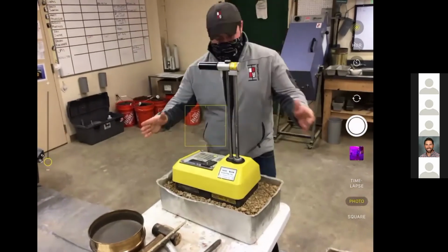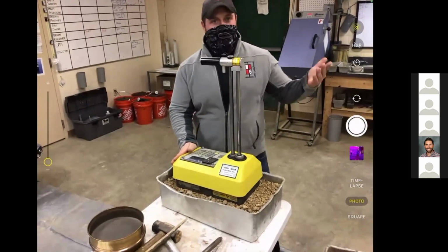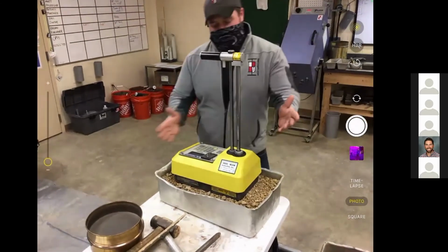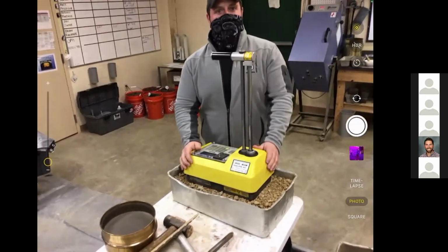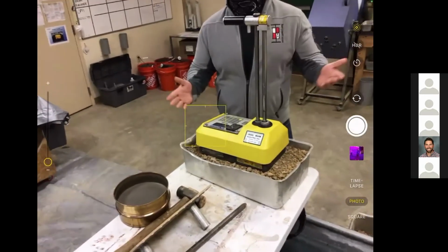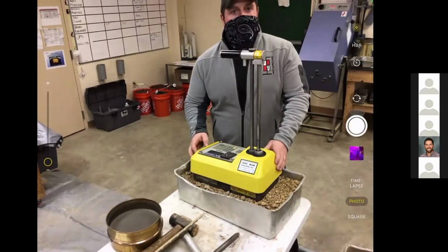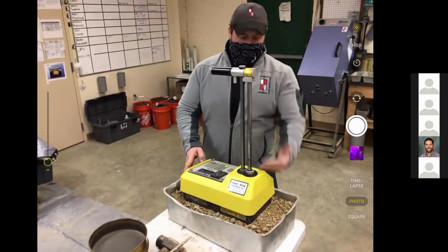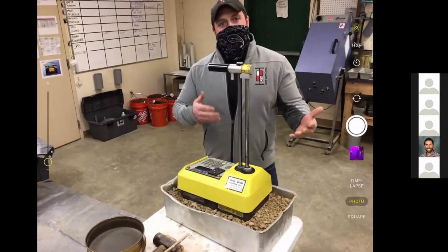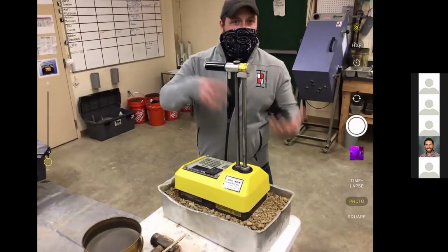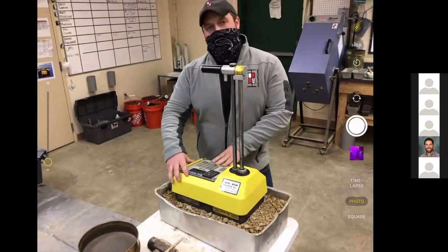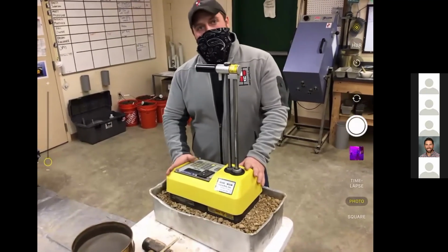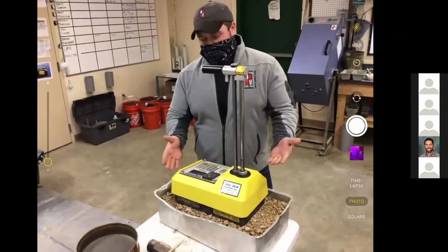All right, so after Brett's done with all the testing, we have the proctor and everything. This is what your new gauge looks like, or they look somewhat like this. They're usually a large yellow orange shoebox, and they're decently heavy. The background behind this is there's basically a radioactive source inside the gauge at the end of this rod. This rod can then lower into the ground once you pound the pin in, and it actually emits particles into the soil. And what that does is the sensor inside this then reads whatever is going through or bouncing back into it. It also can give you the moisture content of that soil that's in place.